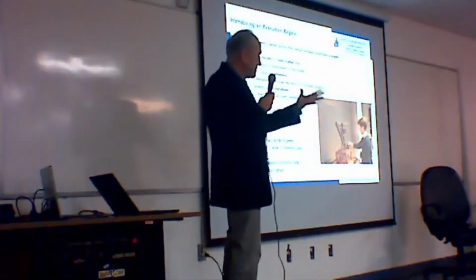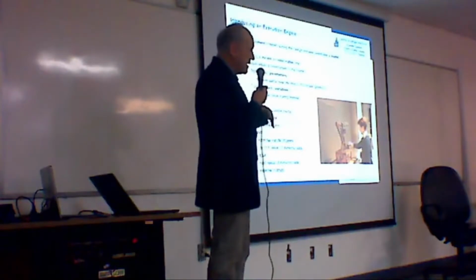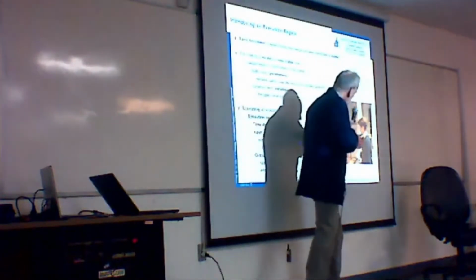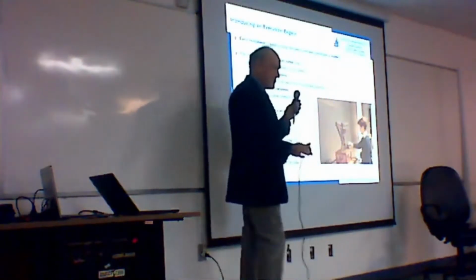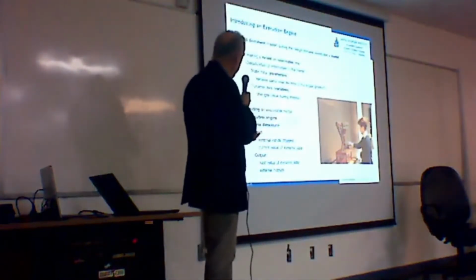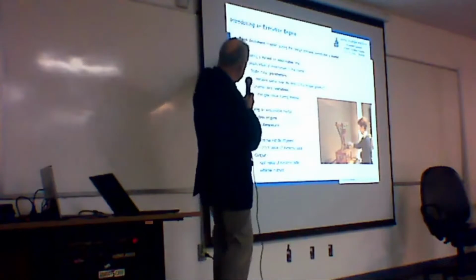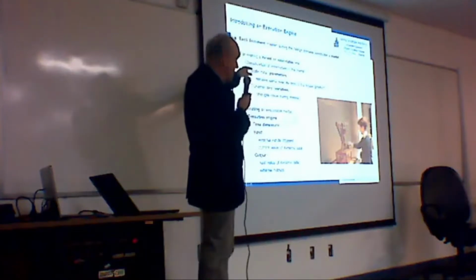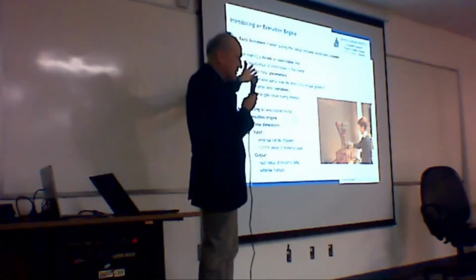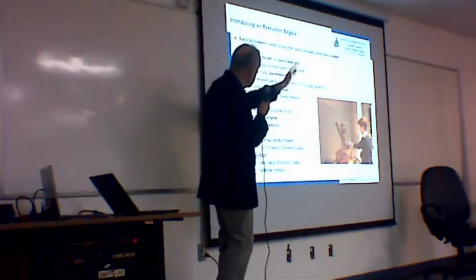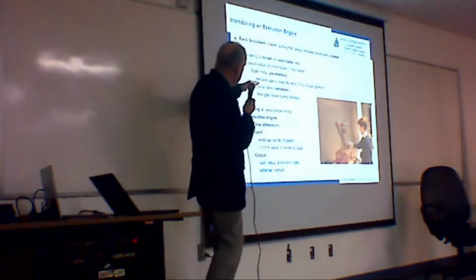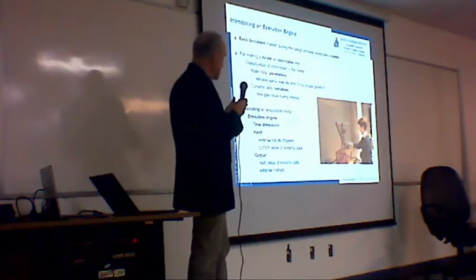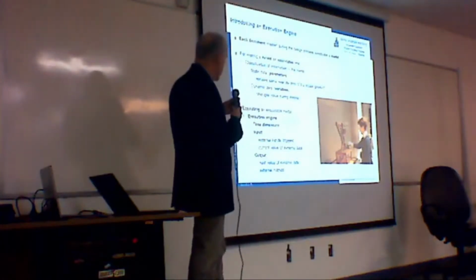Next step is, if we have just a model, we want to bring life into it. So we have here a model, which is static, and then we have an execution engine, which makes this model an executable one. For making a model an executable one, we have first of all to classify the information which we find in the model into static data, mostly called parameters. They remain the same over the lifetime of the model. And dynamic data, we call the variables, which change during lifetime more or less frequently.